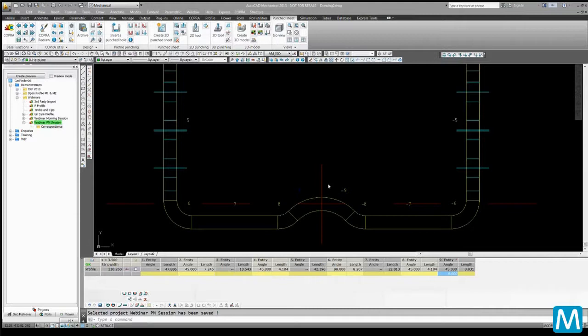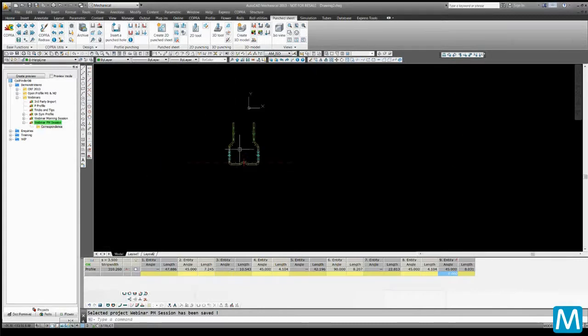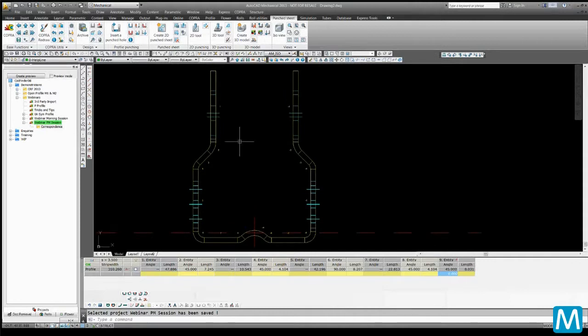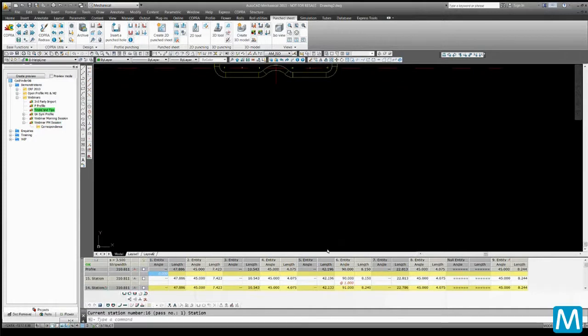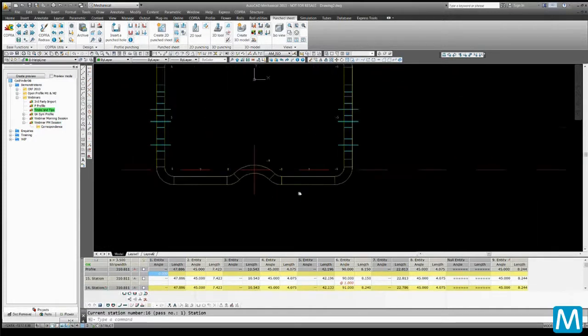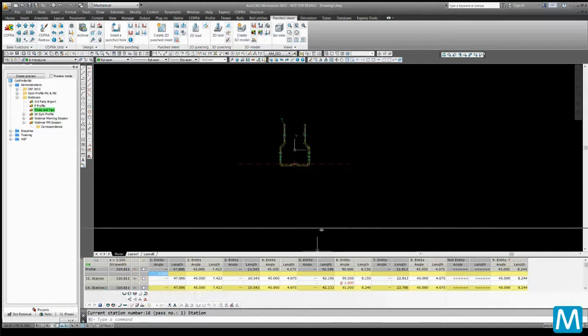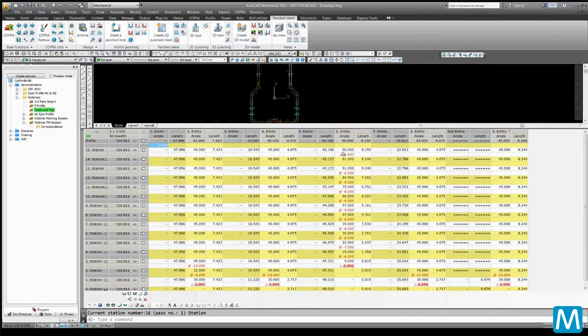So now if we imagine we had a part in the beginning with a successful bend sequence, and now we'd like to take this bend sequence and copy it across into this spreadsheet. So now we can go to that project and hopefully copy and paste the data in here. So I'm going to the Tricks and Tips project, and we can see here we have a shape we'd like to take the unfold data from. Make spreadsheet visible, and here we have an unfolding sequence.